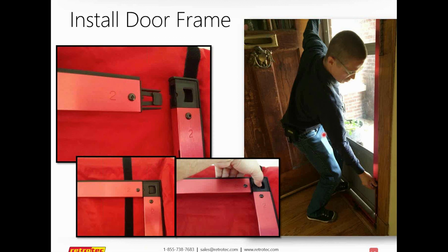Oh, what about the water heater pilot? Great point. Now that I've done this walkthrough with this house, and I've got the house set up, I've actually done most of the work. You do want to make sure that the water heater is set to vacation or turned down, because sometimes you can suck a pilot light out when running a blower door. That will happen, and that can be a nightmare, especially if you have to crawl around on the floor and light those. So,